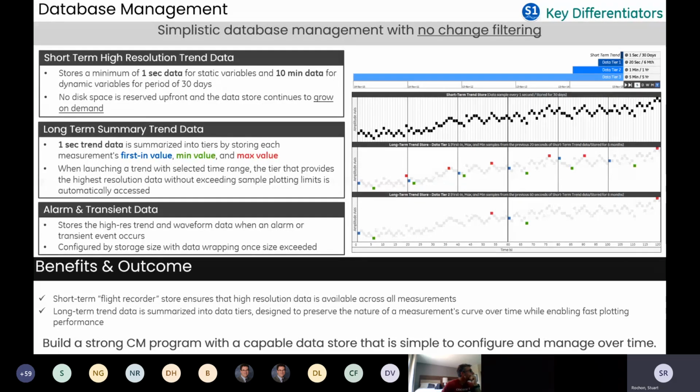The problem with this is you really don't have great control over it. If a point goes erratic, damaged cable, damaged sensor, damage to the shaft, just scratches or something like that that you can't do anything about, it can make the variable go very erratic, and then you have maybe 3 days worth of data because it's X number of samples, and then you're just trying to manage how much time you get out of that number of samples.